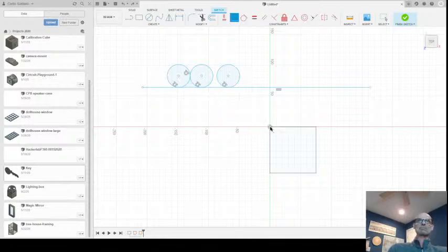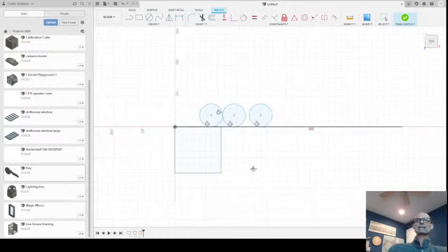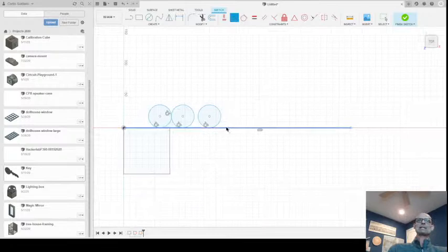In this case, the midpoint is the anchorable item. So I click on that one, click on that one. All right, so now you'll notice that that line has become black now. The highlighted, it's bluish, but it is black, which means it is constrained. It will not move.